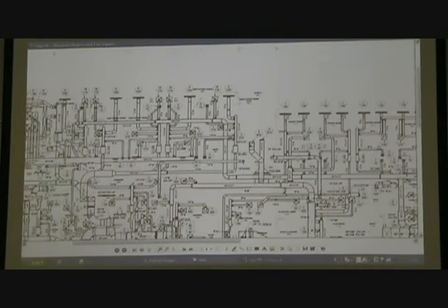But this is ductwork going up to the rooftop unit, branching off, going to other areas, branching off to a VAV box. This is what's called the high pressure duct right here, up to the VAV box. And the VAV box here is going to be a point of pressure change, and all this duct constructed downstream of the VAV box is considered low pressure.